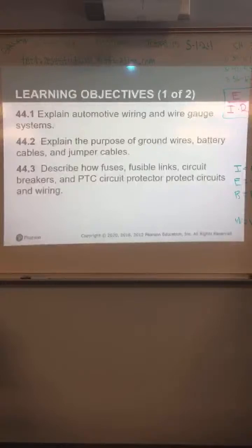Okay, question 1. Tech A says an analog scope can store waveforms for viewing later. No, it can't. B says trigger level has to be set. Does it? Question 1, page 501. Yeah, it must be set. Okay, so it's technician B, right? What's the display called on an oscilloscope? It's called a graticule. B.